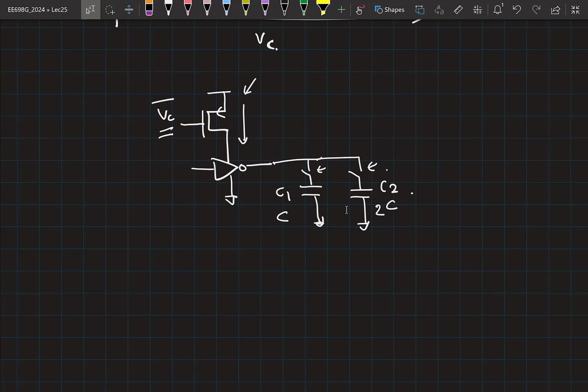If you choose any 4? No, like any 2 different values, you get 4 different. Right, but would it be uniform? That is possible, right? If you have a very specific reason, for example, you know that some distortion is going to happen from the capacitor bank code to the frequency, then you can pre-distort the capacitance values. Otherwise the general method is to binary weight them so that they are equidistant. It increases by step size.